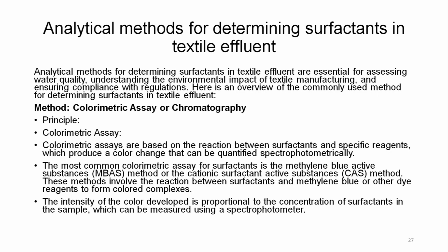These methods involve the reaction between the surfactant and the methylene blue or other dye reagent to form colored complexes, and they will be spectrophotometrically determined. The intensity of the color developed is proportional to the concentration of surfactants in the sample, which can be measured using a spectrophotometer.